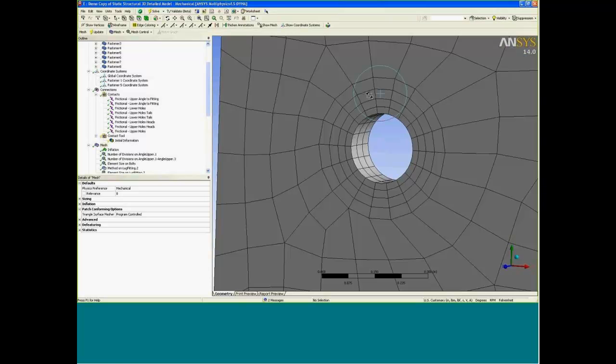In this technique, you define the surface you're going to apply the inflation layer to, and you specify the edge and get those elements radially emanating away from the edge. With mesh constraints, you can get a large number of elements around the hole and have a nice mesh emanating away from the hole to capture those peak stresses, as well as perform some detailed contact setup so you can ensure contact between the holes and the fasteners.